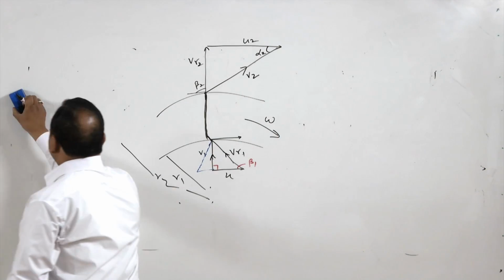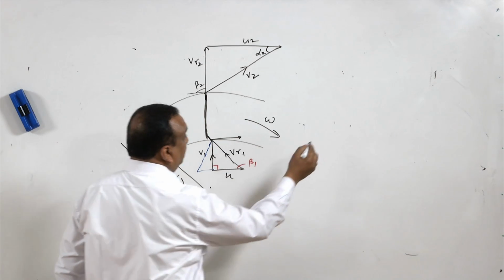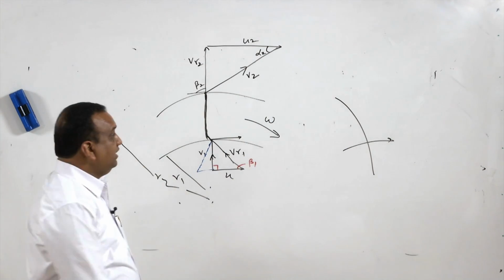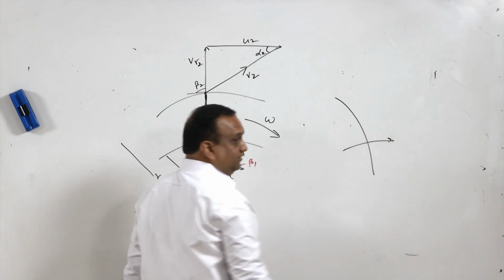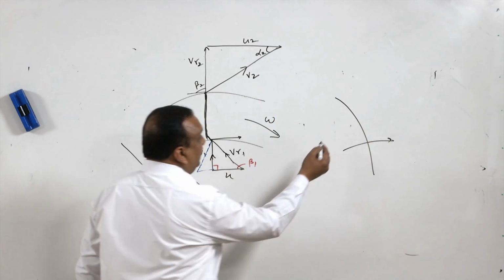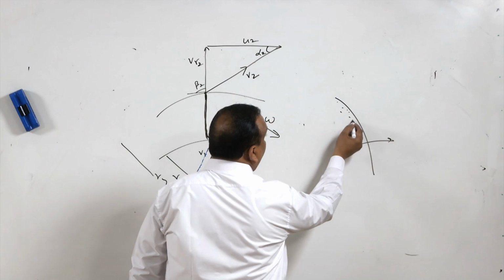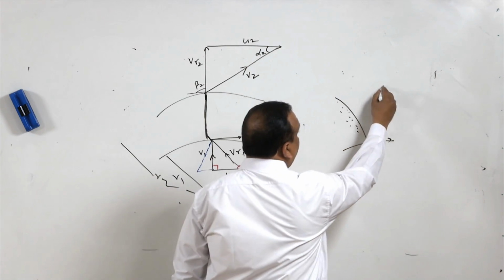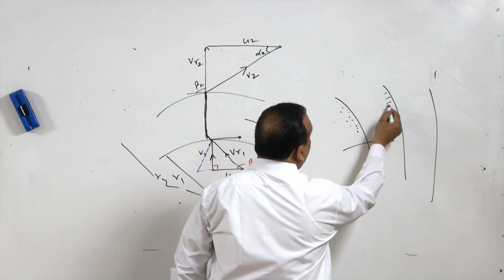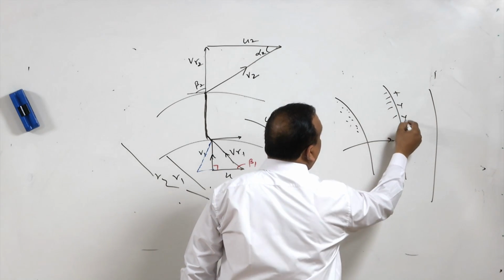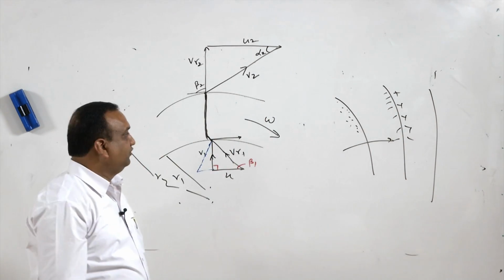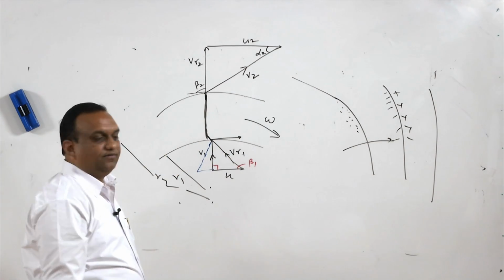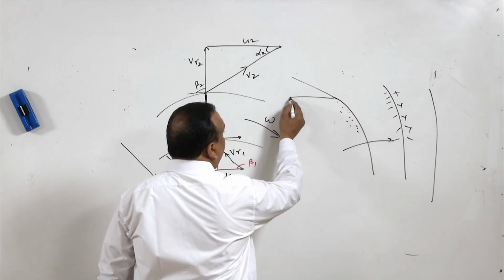The slip factor is when the vane, suppose there is a curved vane moving in this direction. In the leading direction the pressure is high, but in the trailing direction the pressure is low and sometimes a wake is created, right, and because there are a number of vanes, on this side there is a negative pressure, on this side there is a positive pressure. So instead of leaving in this direction, the fluid tends to leave in this direction with a certain angle.